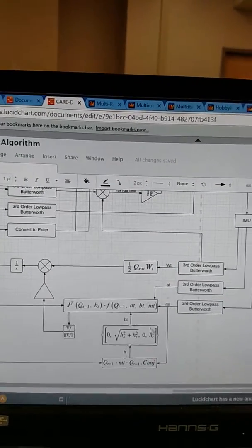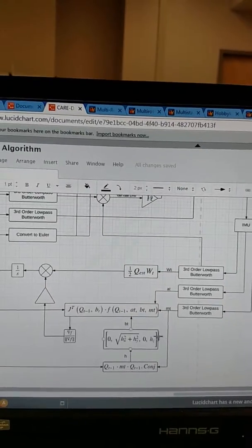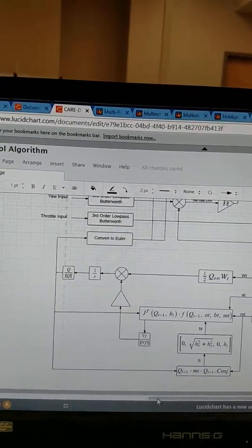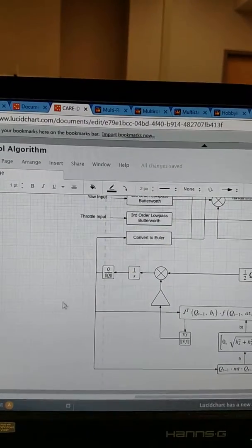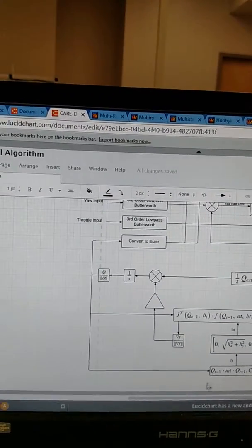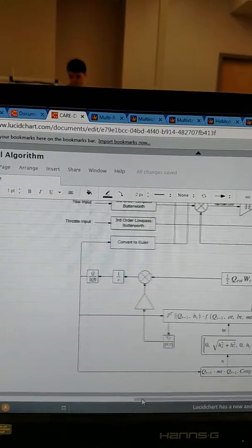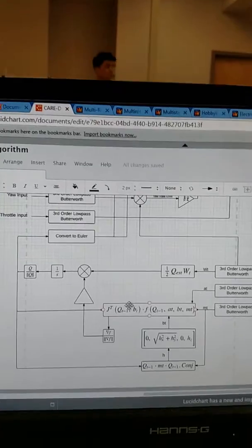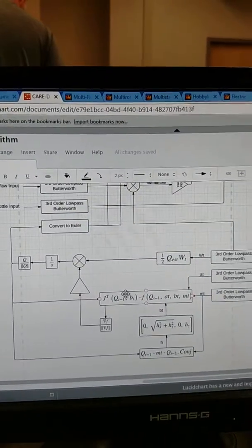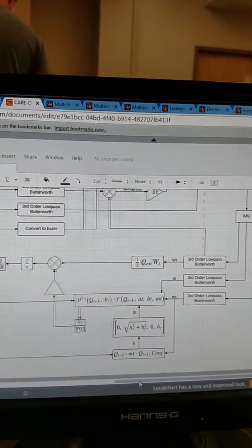This is what's called Group 1 out of the MADRC algorithm according to his dissertation. We did not implement the Group 2 PID controller, which would have been a second PID controller out over here that would account for gyroscopic drift. We chose not to implement that one because we would not be running more than 15 minutes. If we needed to go longer than a 15-minute flight plan, we would have needed to implement the Group 2 part of the feedback loop.